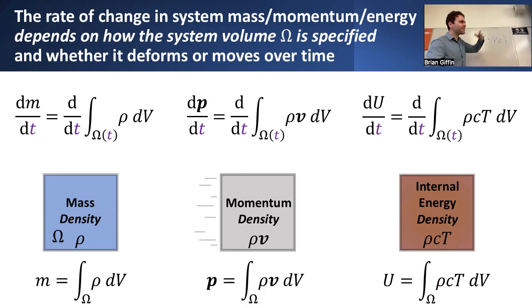So we've transformed everything into equivalent volume integrals involving these different quantities of interest, but there's still something that we have to deal with. And that's, well, how do we actually measure this time rate of change of this conserved quantity that we're looking at? In particular, the time rate of change of mass, or of momentum, or of this internal energy term, thermal energy in particular.